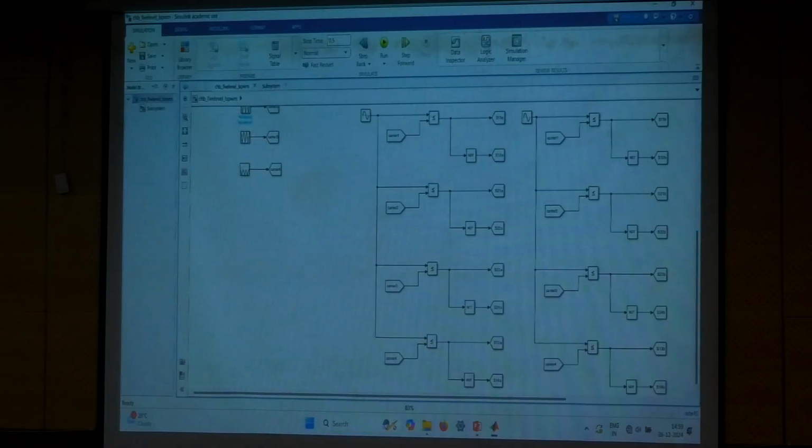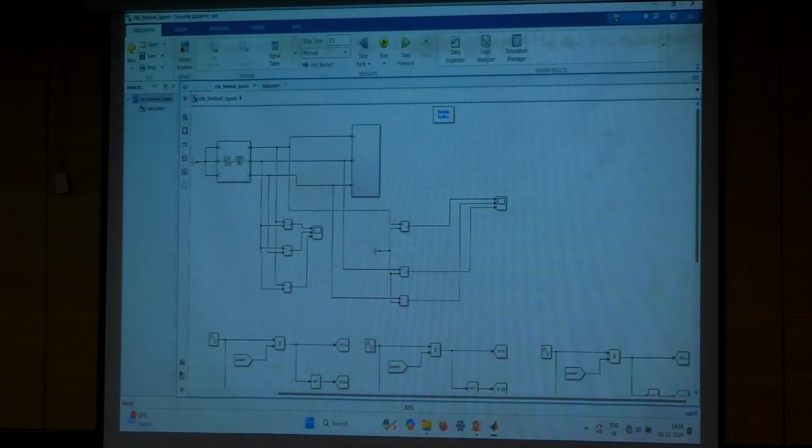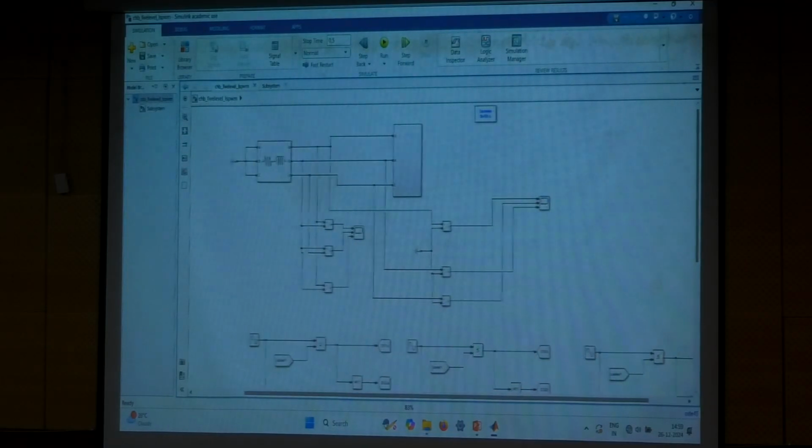For example, here A phase S11, 1 2 1 bridge, first bridge, second bridge, or A phase B phase, so that you need to know, right? The same thing is there for the B phase and C phase as well. The only thing is that the modulating signal is shifted by 120 degrees and further shifted by 120 degrees for the C phase. Alright. So we will run this one, and also for simplicity I connected some RL